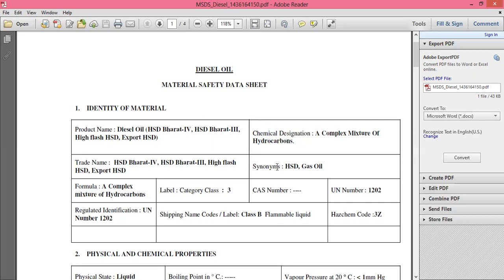For example, for the chemicals which we keep in the chemical locker, we should also receive this MSDS, and we should read this MSDS before handling that particular chemical. For paints and thinners also, we get this MSDS. They're normally kept in the paint locker. Wherever this particular dangerous good is kept, the MSDS is posted outside. But because of laziness or negligence, we don't read this MSDS. We just go, wear some gloves, and start working with that particular dangerous good, whatever it is.